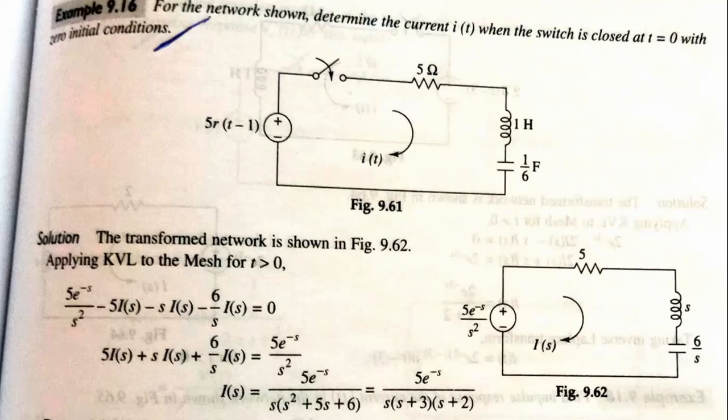You should remember how we can simplify, how we can do the partial fraction, how we can keep it in the standard form. So that we have tried here in the I of s. This is an important equation while you are going to write the I of s. Totally depending upon the I of s, you can simplify the entire circuitry. So see here, 5 e raised to the power minus s will be the numerator, as it is. After segregating s square plus 5s plus 6, you will get s plus 3 and s plus 2.